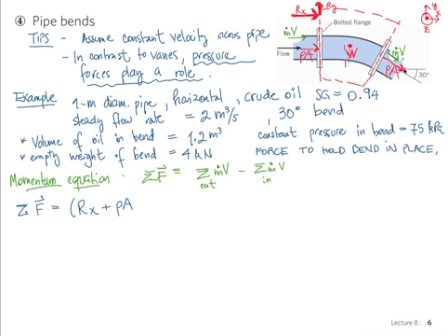pressure here also. Yes, I've drawn the pressure wrong in my picture, okay? Because we always draw pressure as acting normal to any surface, right? So the pressure couldn't be pulling. Pressure is always pushing, correct? So I've actually drawn the arrow here in a way that is not entirely correct for the purposes of considering fluid pressure. Fluid pressure always acts perpendicular to every surface. So forgive me for that confusion.